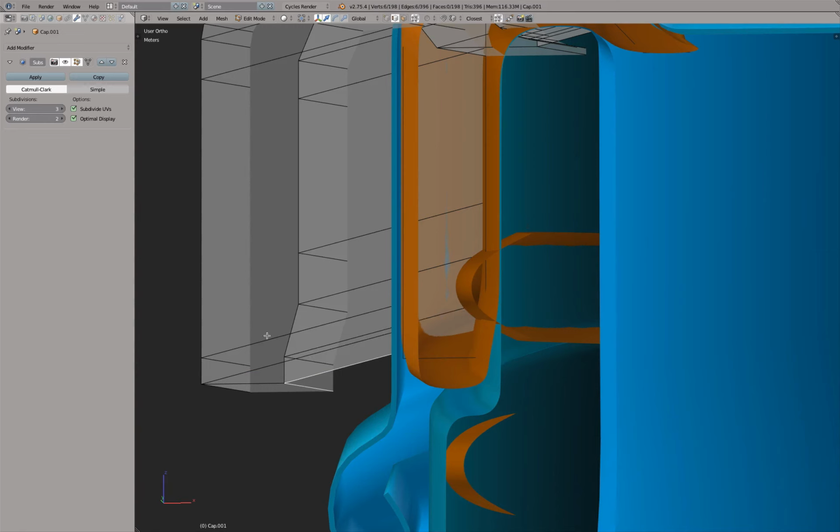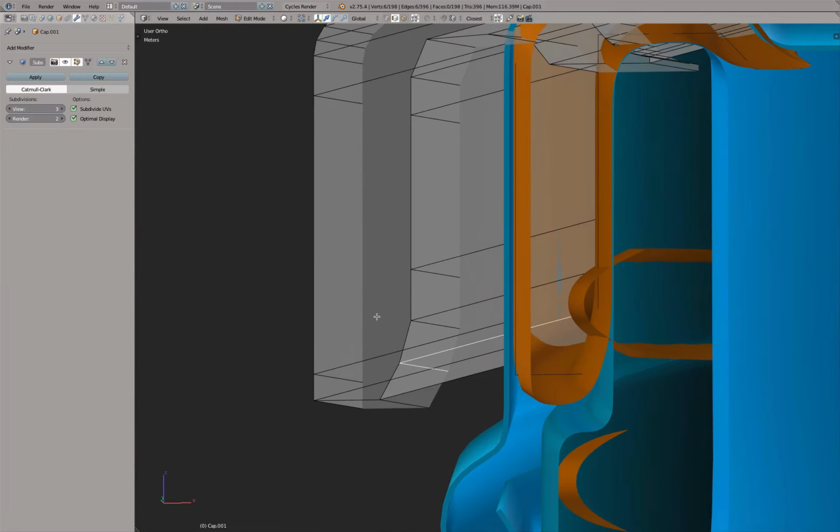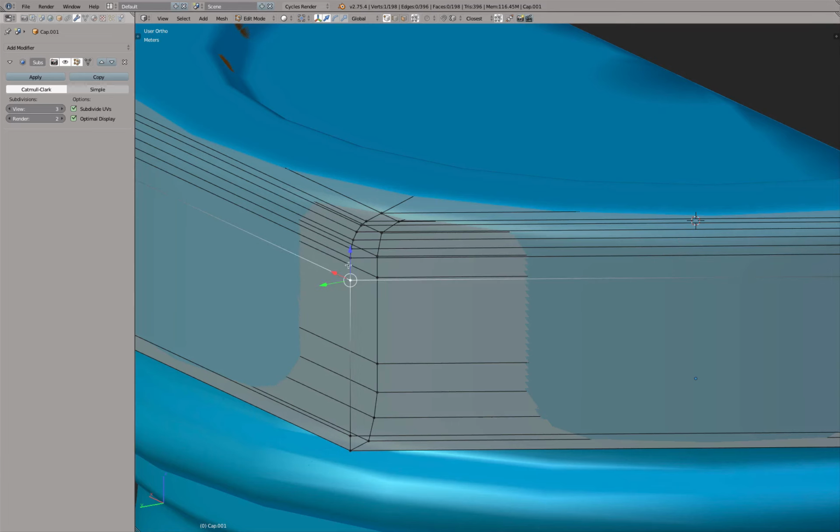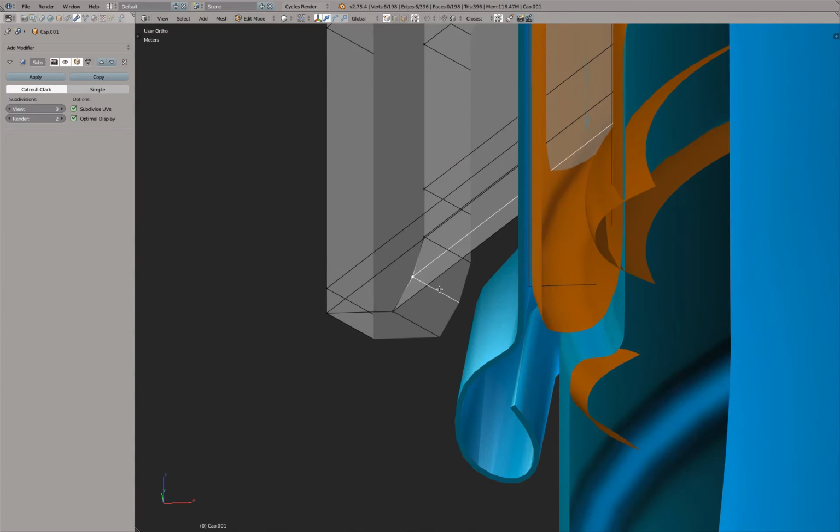So you see we're actually opening this a little bit. And then GG, we can slide it again. Different way to explain what this GG actually means. So I can move this one up and down, left and right along the axis. If I press G, I'm just in freeform move. If I press G a second time, you see I actually slide this point along an edge. And this also means when you select a loop, you can GG, slide it to the one side or slide it to the other side.